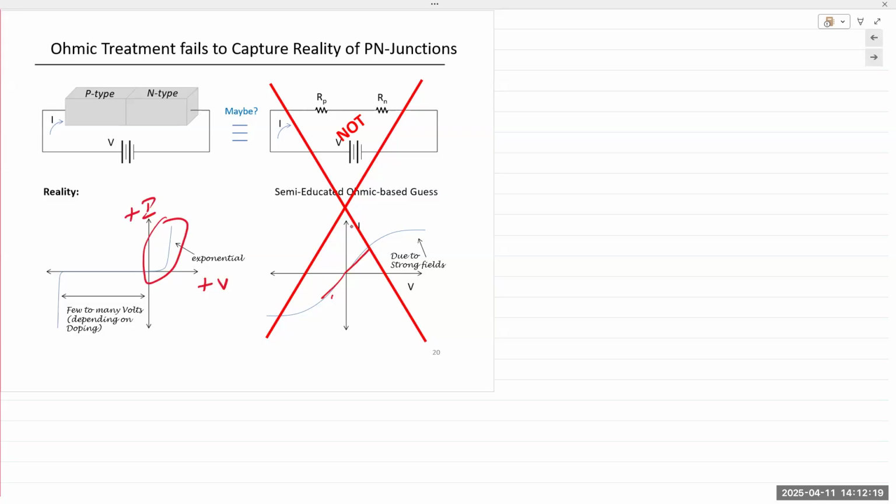That is indicated by this region, where it's nearly equal to zero. Voltage increases, but current stays zero. Then as the voltage starts climbing, slowly but surely, current starts increasing. After a certain point, it's an exponential rise in the current. From that point on, a very small increase in voltage, millivolts, will cause a large increase in current. So the response was non-linear.